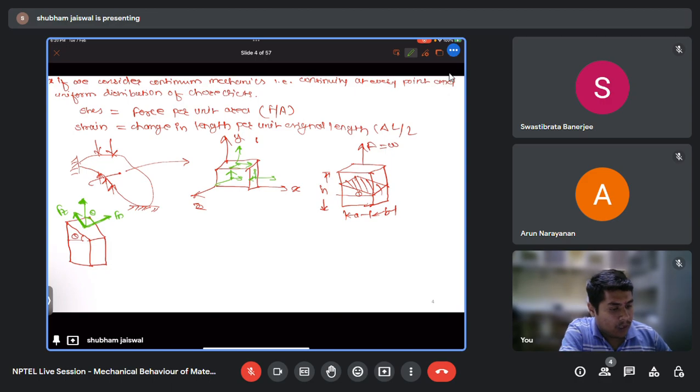And let's say this is our x prime axis, this is our y prime, this is y, this is x. Okay, and then we have calculated the normal force acting on this, that is the cosine component of this force F, that is Fn is equal to F cos theta, and the tangential component will be, anyone? So F sin theta.